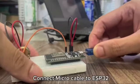Copy the coding from module 1.1 and then upload to Arduino IDE. Compile the coding. Upload the coding to ESP32. Press the boot button for 3 to 5 seconds while connecting status. Look at the output from serial monitor. Because we get 0 for our threshold value, we need to rotate the potentiometer to get our threshold value. So the threshold value changes as the potentiometer rotates.